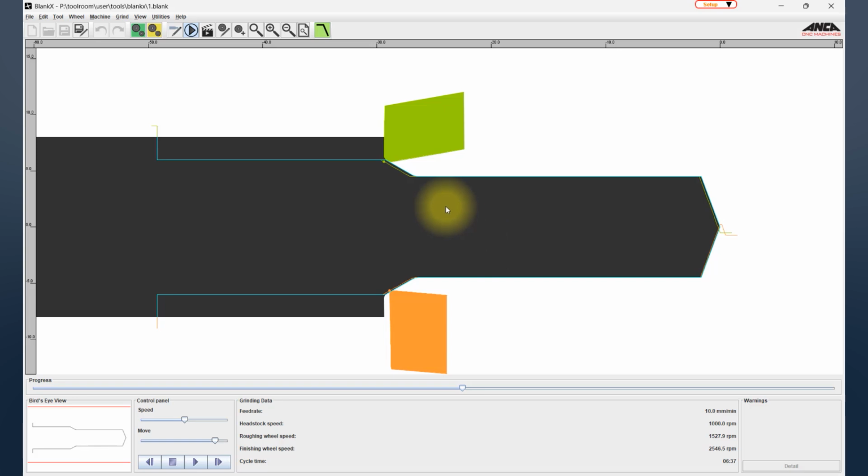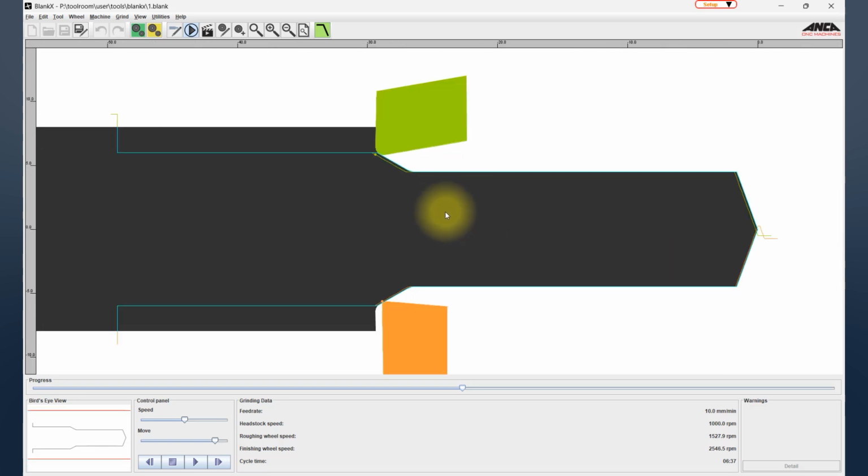Now again, one more thing to note here is the software assumes that the radius entered is concentric to the center, uniform, and if any error in the actual grinding wheel on the machine, the software wouldn't know. Plus the other thing to note here is the radius needs to be as close to the physical radius on the grinding wheel. Otherwise there's not going to be a match between the result what you're seeing here.